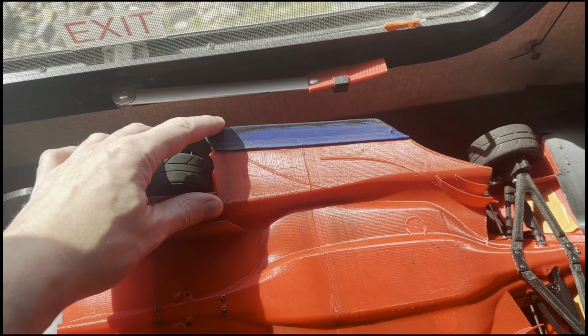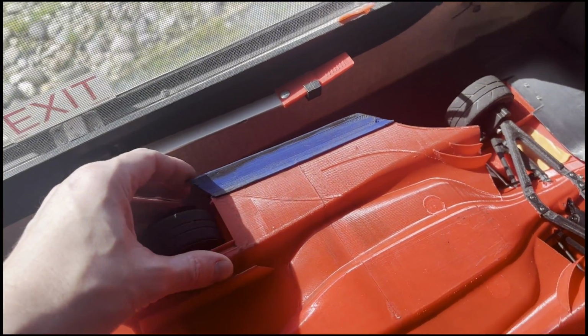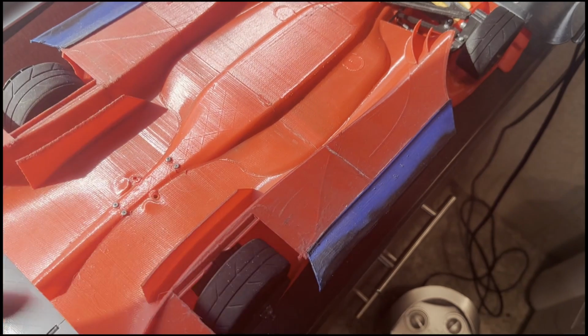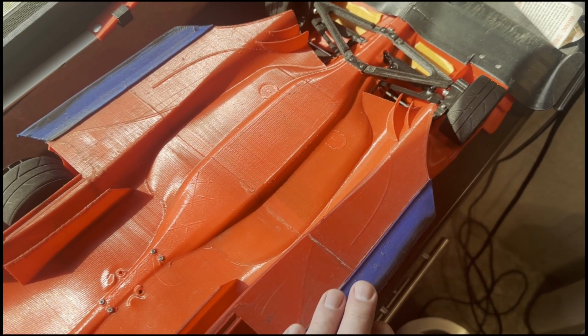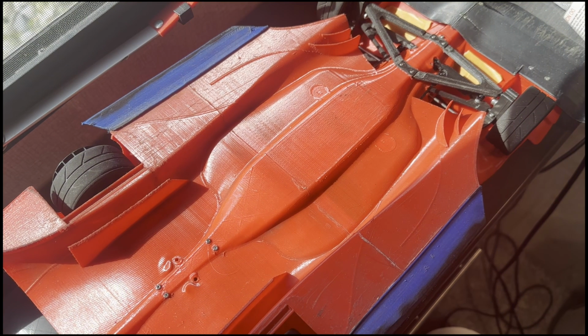flexible edge skirts. The underfloor generates a lot of low pressure over a really big area. Unfortunately, because it's such a big area, that means there's a lot of space along the edges for the high pressure air above the diffuser to leak under the floor and ruin the efficiency of the diffuser. So most full-size race cars run very close to the ground to minimize this effect of the edge seal leaking, or they run different vortex type sealing structures.